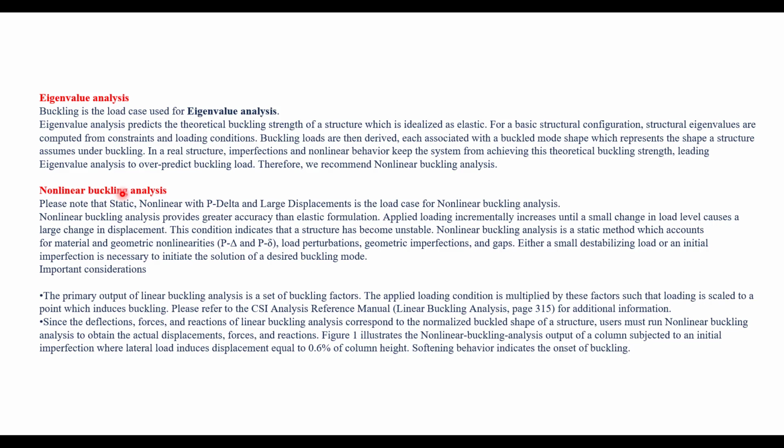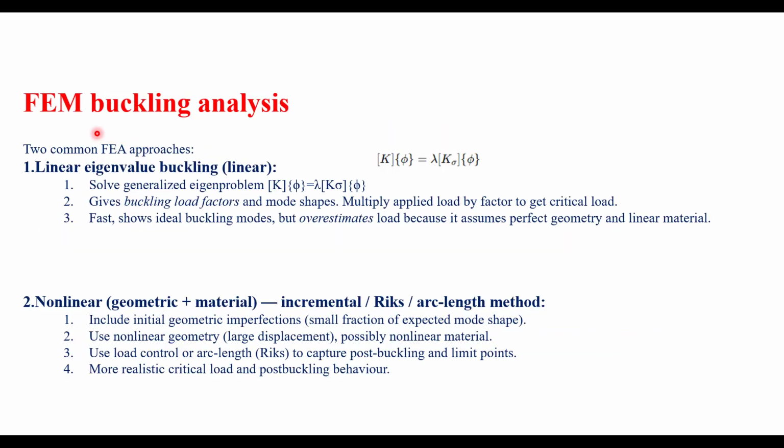So what we do exactly at the back end as a CAE analyst is we check all these things, and we always have a buffer. Okay, well, just to get deeper into linear and non-linear buckling, you can see we have two scenarios. If you want to do the buckling analysis, you can simply carry out the linear buckling analysis, that is linear eigenvalue buckling.